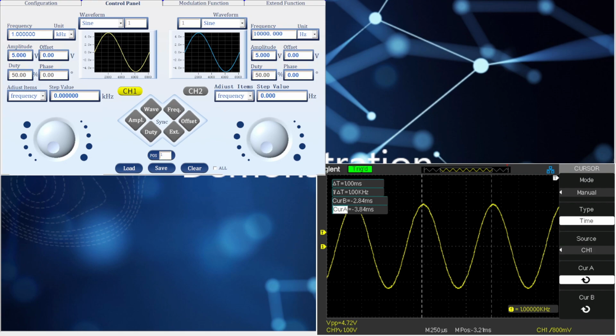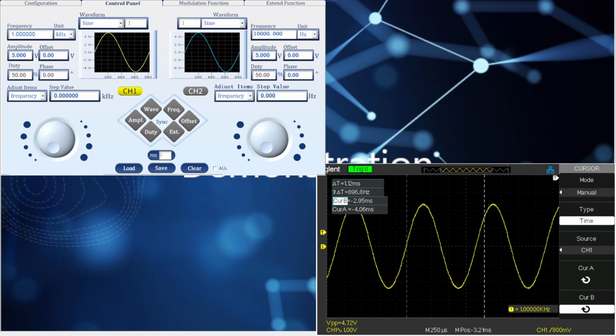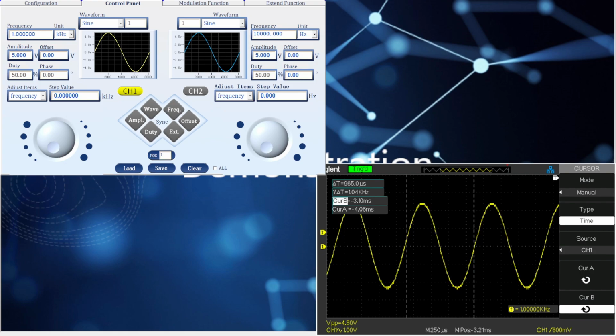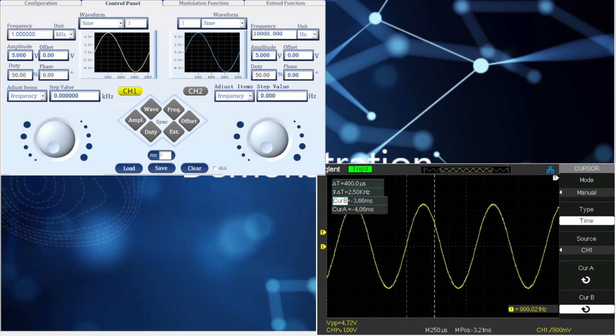Well, in order to make that manual measurement, we go from leading edge to leading edge. Now, unless specified otherwise in, say, a technical manual, you generally make measurements from the leading edge of your signal to the leading edge of the second time period. The trailing edge, didn't mean to make it smaller, would be on the downward slope. So say from here to here.